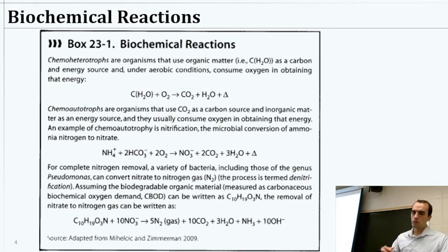They can actually take CO2 and essentially use that as a carbon source, so then we can get some ammonia removal that way, or denitrification. So we take ammonia, and so this is dissolved CO2, so bicarbonate here, and oxygen, and we're going to end up with nitrate there. Probably get some nitrite first and then nitrate, CO2 and water and heat.